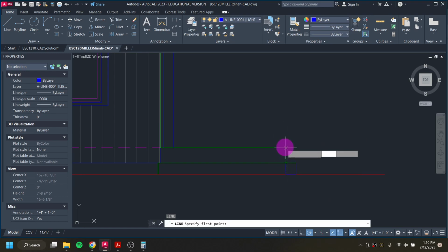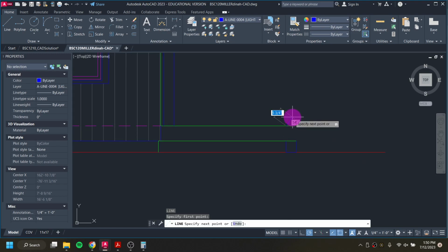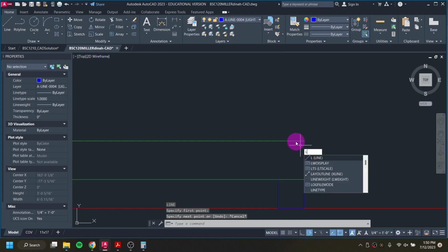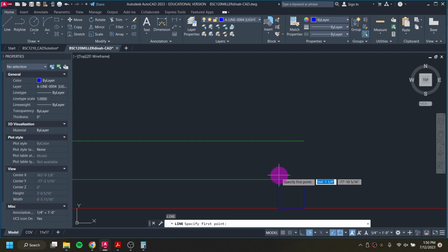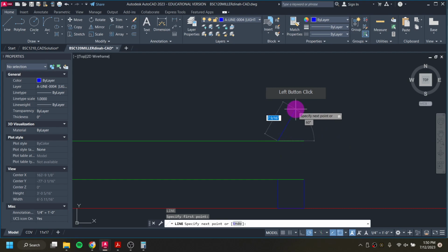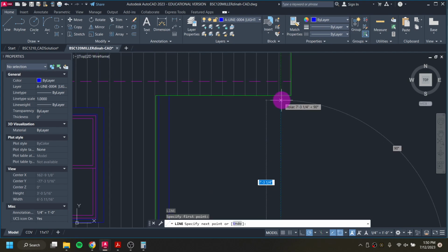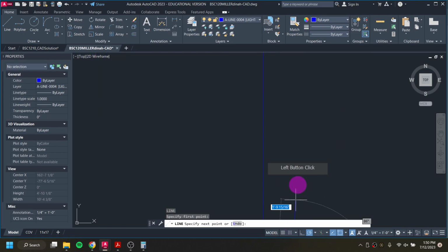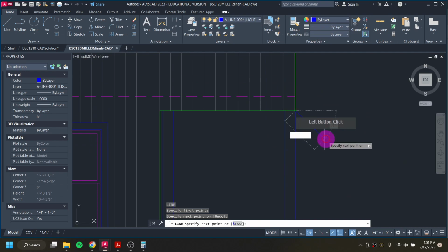And then I'll draw another line from here. How I got it to start here was when I went into the line tool, L enter, I hover over without touching, without clicking, and then I can track to where it would meet. Enter to end the command, enter to get back in the last command I used. Here.